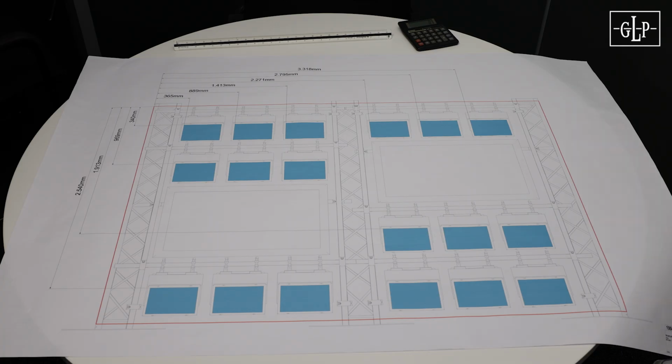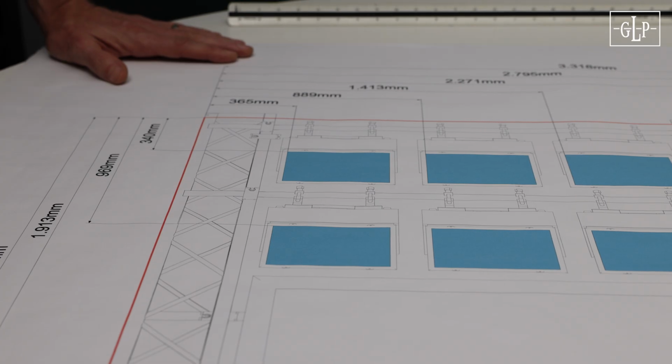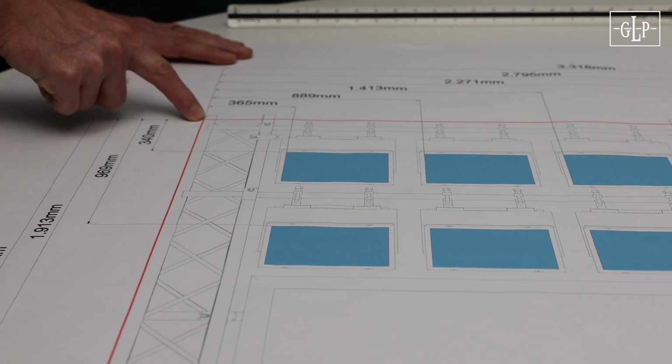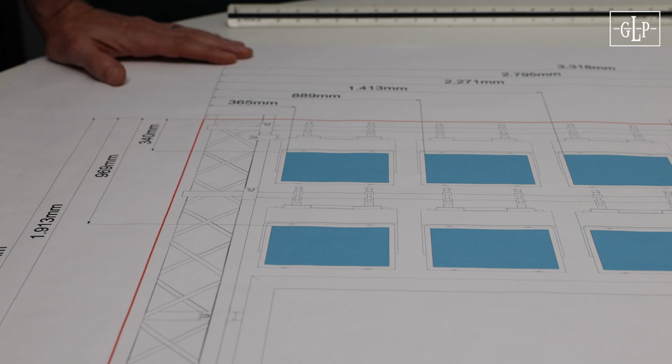In the next step, we determine the physical positions of the devices from the plan or directly from the software. Here is a drawing showing the device positions in millimeters relative to the origin in the upper left. Once again, we calculate the resulting pixels from the physical lengths. Since the first pixel in the coordinate system origin starts with a coordinate x and y at 0, the pixel value must be decreased by 1.